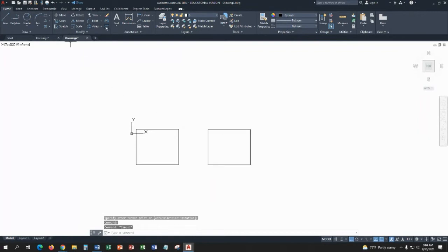So the next thing that we did was we offset. And we offset 6 inches. So I just type in 6. I don't need to type in inches because if you don't type feet or inches, it automatically assumes that it's inches. So I'm just typing 6. And if I go to here and I come to the inside, I've created an inside loop on my screen. I'm going to go over here and go 6 inches in on this one too.